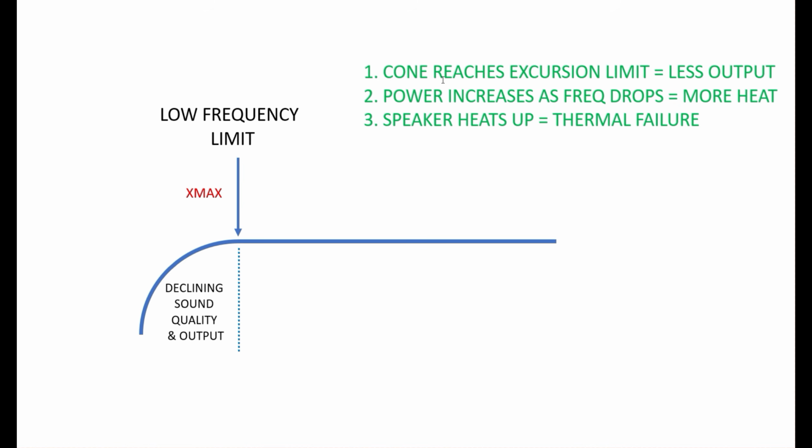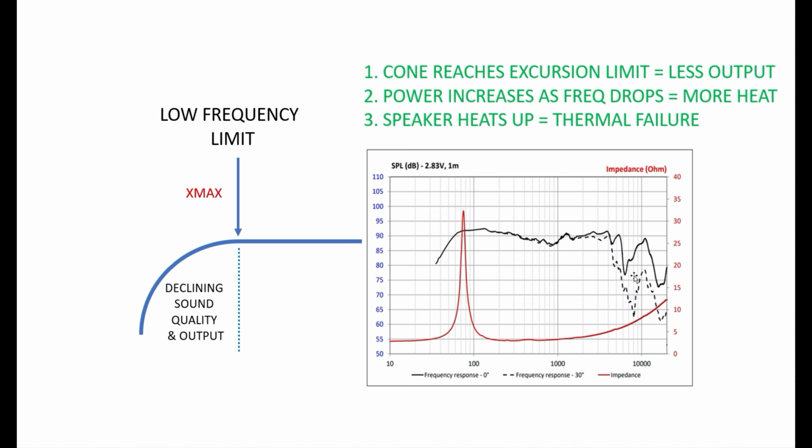And to move all of that air, you need more power. More power means more heat. So the more you try to push it, the more heat you generate, and eventually you end up with thermal failure, right? The adhesives in the speaker start to melt, or the voice coil burns out and fuses, or whatever. And we kind of looked at this a little earlier when we talked about X max and X mech, right?